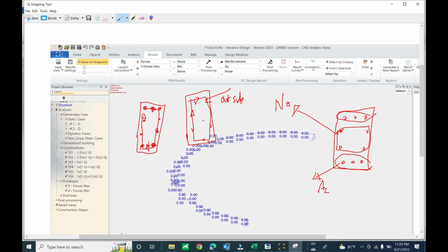You must make the outside link larger, up to 10 mm or 12 mm, to receive the torsion, and with the maximum spacing and minimum spacing. And the internal link, you can design it to receive the shear.